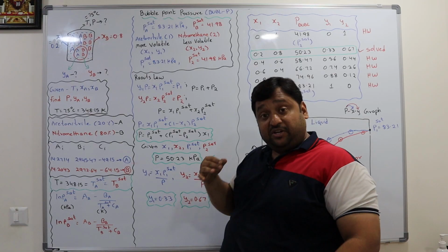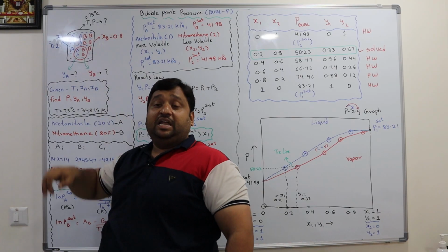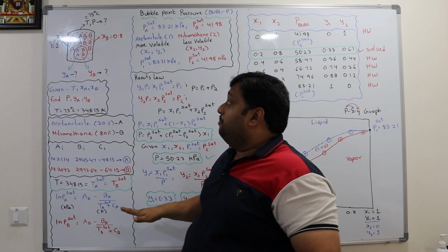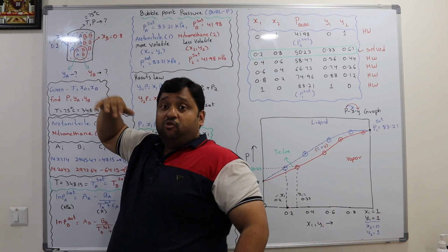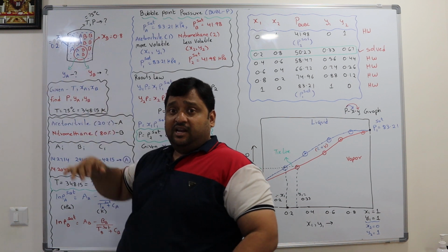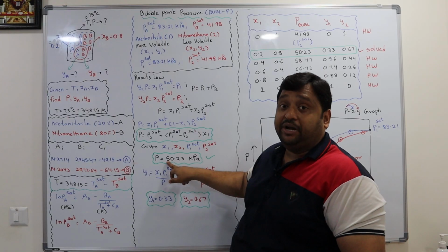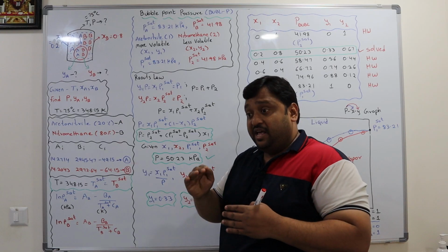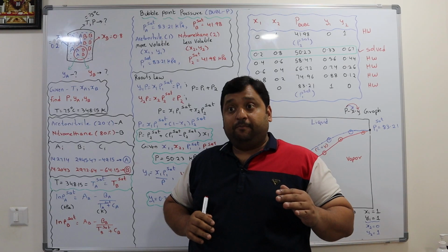Of course, the bubble pressure will change depending upon the composition of liquid you are going to take. So same procedure you have to apply, okay, because I have done the sample calculations of 20% and 80%, and you can redo the calculations for 40%, 50%, 60%. Like that you can change the liquid compositions and see what are the pressures you are going to get, because for every composition there will be a different pressure, okay, because if you take the pure component, if you take